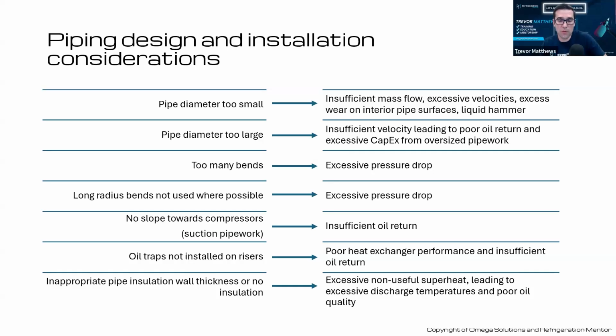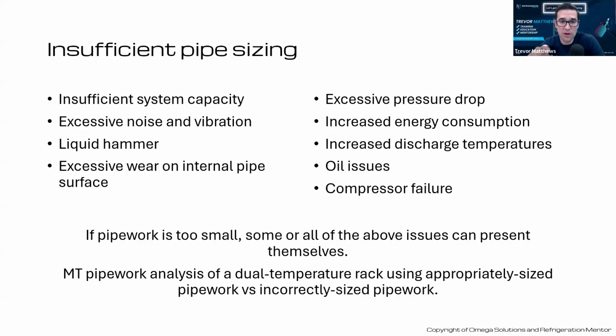And this is something important when we talk about that design program: when you're calculating the price for your customer, this is important because that insulation is expensive. So you've got to calculate for that, because if you oversize it, just like we said, there's more refrigerant potentially. If you don't have that insulation, or thick enough insulation and a good insulation as well, because we see lots of insulation that breaks down very quickly. So that is important for that pipe.